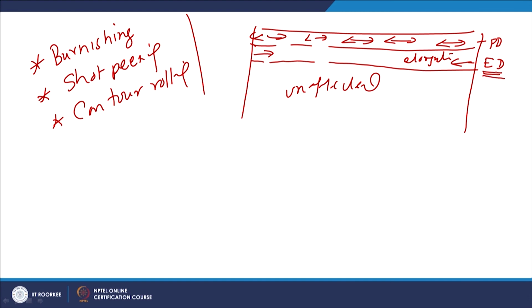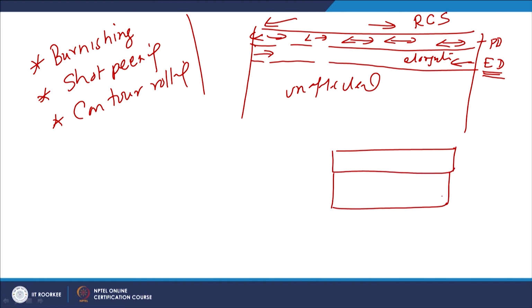The elastic deformation tries to regain the earlier conditions, and because of this the surface layers experience residual compressive stresses. The surface layers are subjected to tension under plastic strain conditions, while the subsurface zones were under elastic deformation. The subsurface zone tends to come back, while the surface layers remain there. Because of these two dissimilar conditions experienced by the two layers, surfaces experience residual compressive stresses.